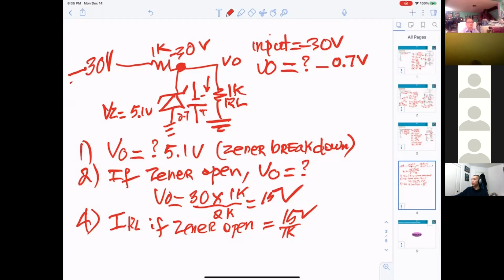They're just working like normal, when the anode is higher than the cathode, and you substitute the battery. It's the same 0.7 voltage drop. If you start with 0 on your positive side, then it's negative 0.7. However, you have to pay attention to the polarity. We already told you, if it breaks down, review this thing here.